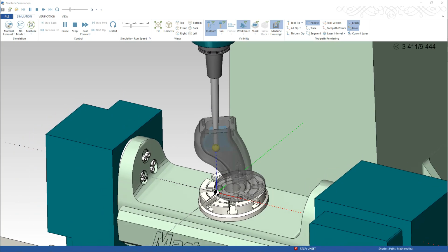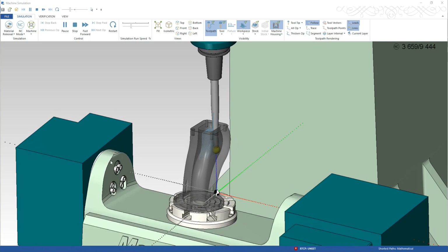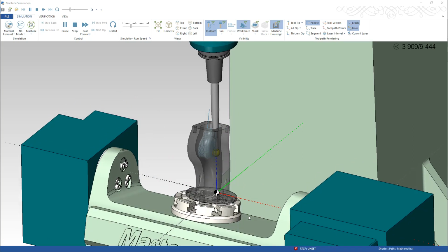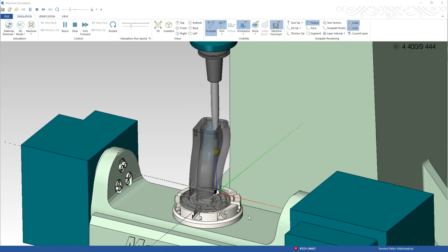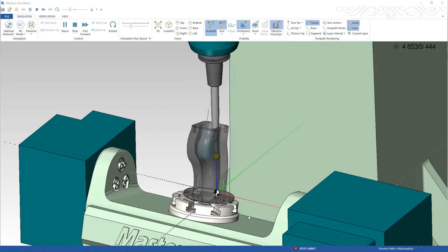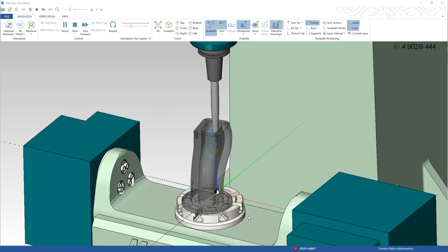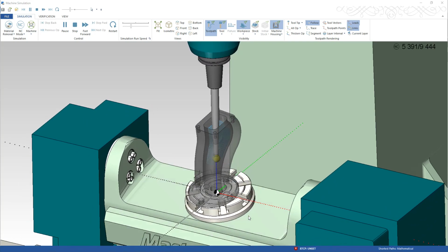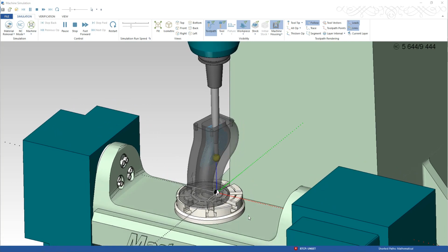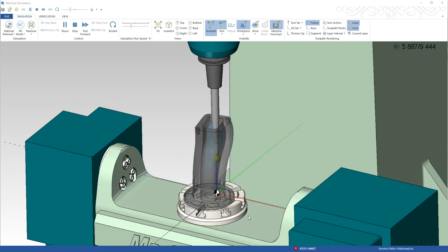And the motion's pretty even in my rotary axis parallel to the X, which is typically the A axis. Pretty even front to back, so I see no reason to tell Mastercam to say, no, I only want to have the tool tilted to the front or tilted to the back. That looks like the A axis rotation is even from side to side.